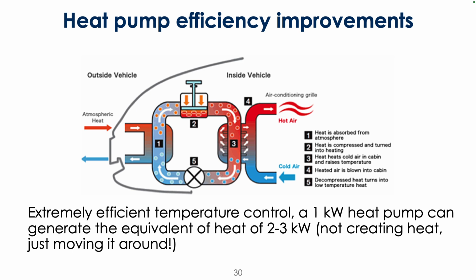A heat pump really is essentially like an air conditioner in reverse. You're drawing energy from the surrounding air. This has been implemented in a small number of electric vehicles at this point. Some models of the Tesla Model 3 have it, the Hyundai Ioniq 5 has it, for example, and a couple other vehicles are starting to implement these. These will operate much more efficiently, and you won't see quite the same reduction in range and efficiency when you're in really cold climates with EVs.